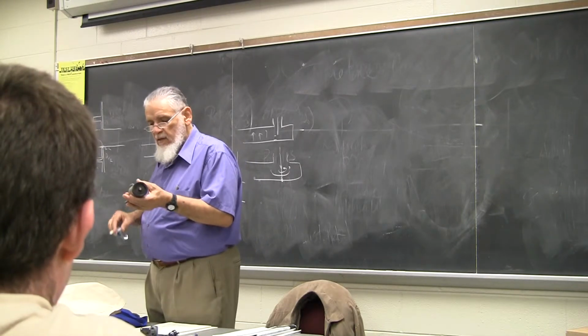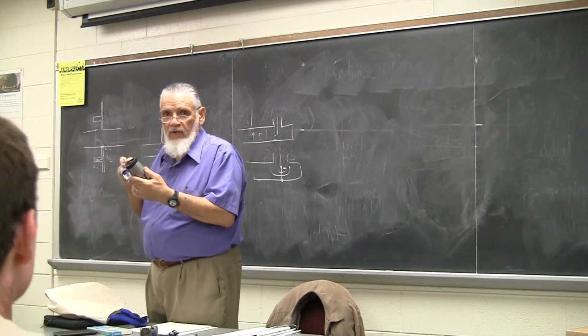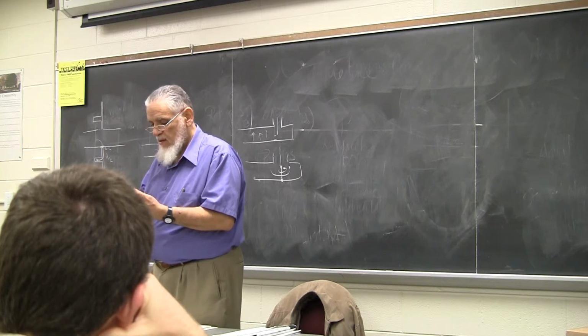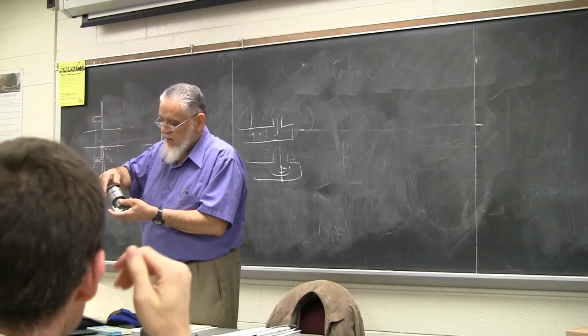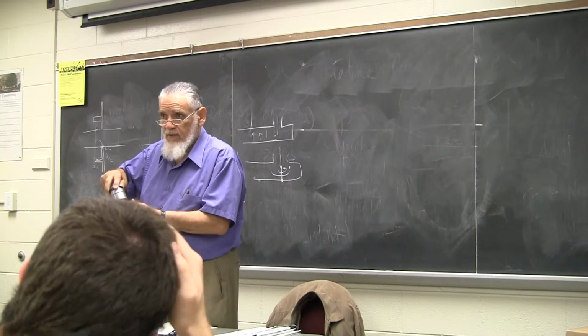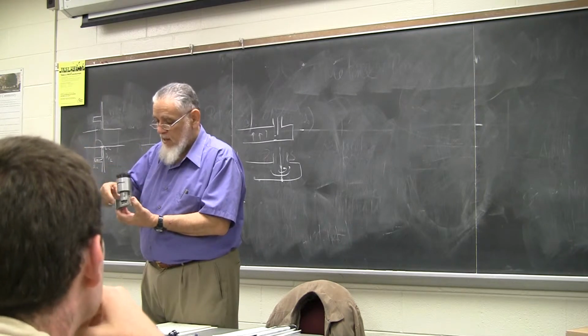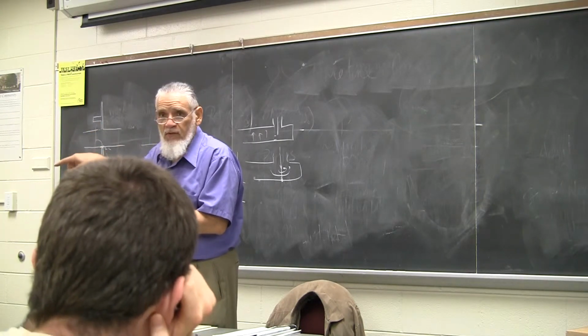Last but not least, that's a piece of guide with a cavity resonator sitting on top. And the cavity resonator is calibrated in resonance frequencies. So you put that on your waveguide and you monitor your signal flowing through and you look for a resonance, right?